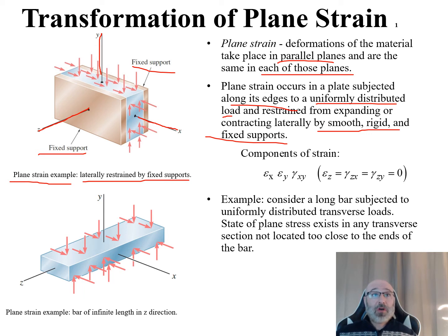And we can also see our loads coming along the top here, like this. This is going in our positive x direction, and we can see some coming down in our negative y direction. We have these coming up in our positive y direction right here, and these coming in over here in our negative x direction. So pay attention to your sign convention, pay attention to your coordinate system, and make sure that those mesh.